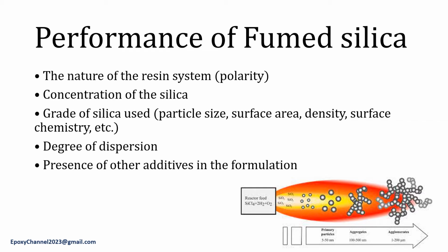The thixotropic characteristics provided by fumed silica are due to its ability to develop a loosely woven, lattice-like network by hydrogen bonding between particles. This network raises the apparent viscosity of the system, increases the cohesive forces, and contributes to the suspension of the solid. Because the hydrogen bonds themselves are relatively weak, they are easily disrupted through the action of an applied stress or shearing force and quickly reform when the stress or shearing force is removed.